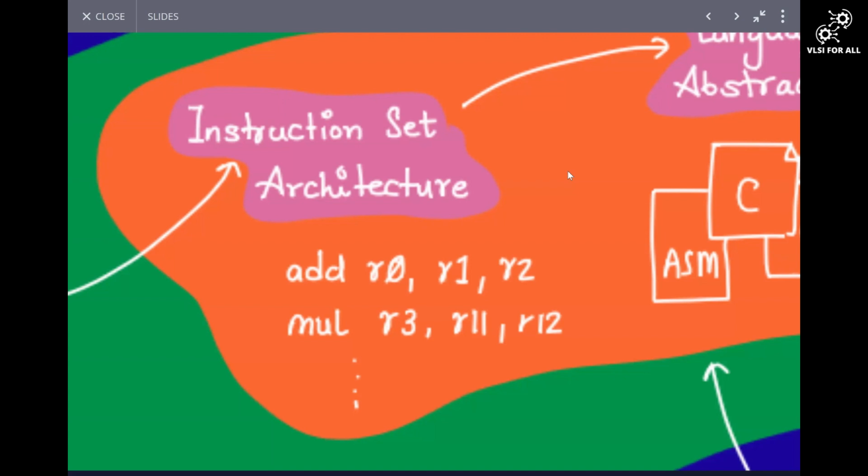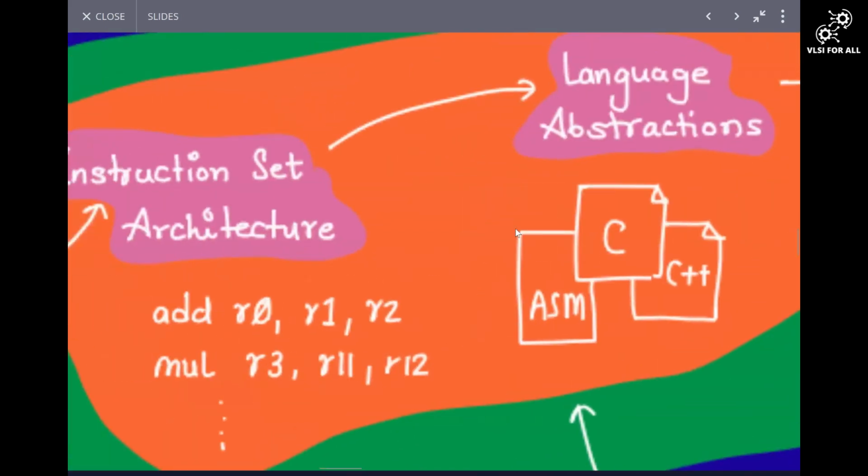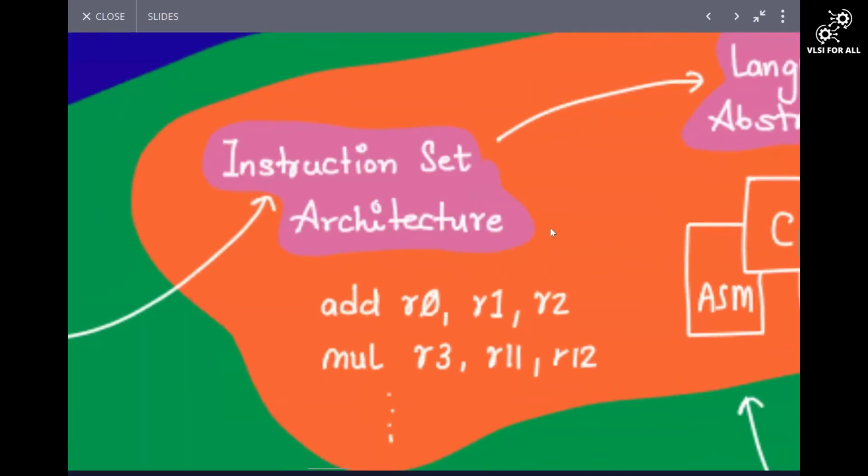So if you take an adder as a simple example, carry look ahead. Yeah, half adder is just an adder. Let's say AMD might be using a carry skip adder, or Intel might be using a carry look ahead adder. We don't know. I'm just taking an example. So their microarchitecture is different. Got it? So I just wanted to talk about what an instruction set architecture means.